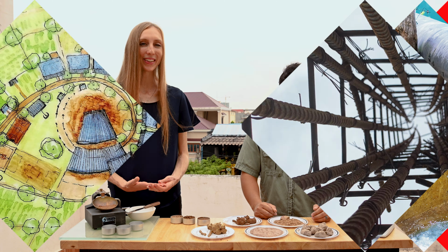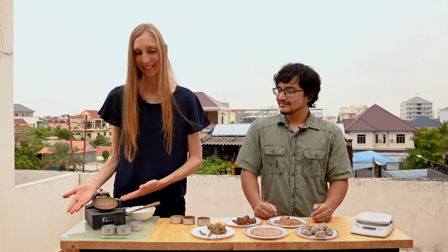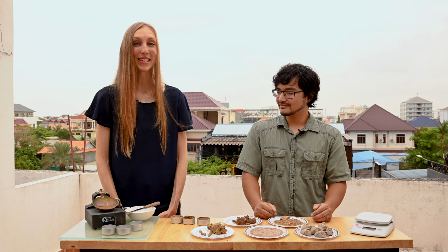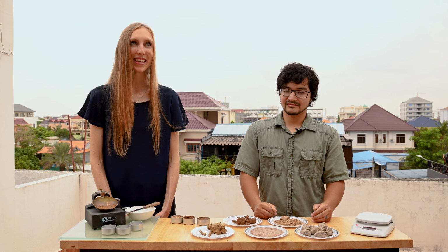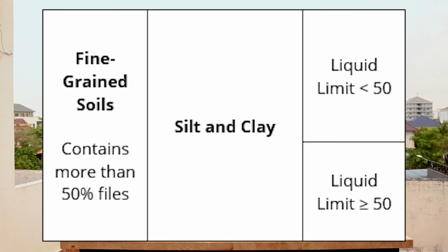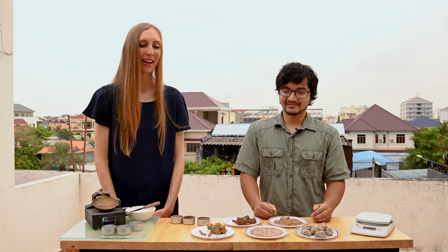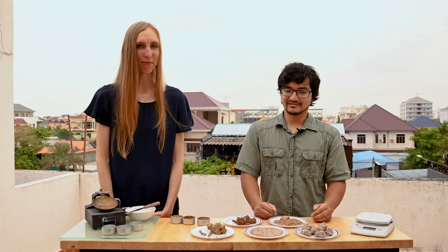For fine soil, you can use the Atterberg limit test, which we have here and will be described in a separate video. This test can be used to distinguish between the fine-grained soils of silt and clay, which are hard to distinguish in the field.